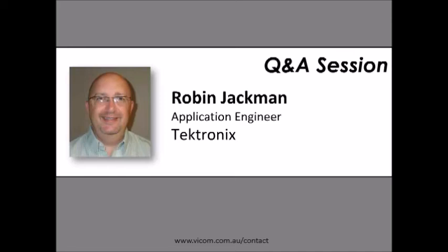The next question is, you mentioned in the beginning of your presentation that antenna factor was not the same as antenna gain. Can you please elaborate? Antenna factor is a function of change of energy versus impedance. And there are some very good documents out there that show the mathematical relationship between antenna factor and gain, and how you can take the antenna factor information and make up a table so that we can fill out the amplitude or gain offset in a specific measurement receiver or spectrum analyzer.